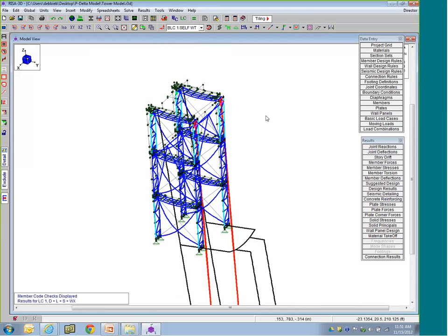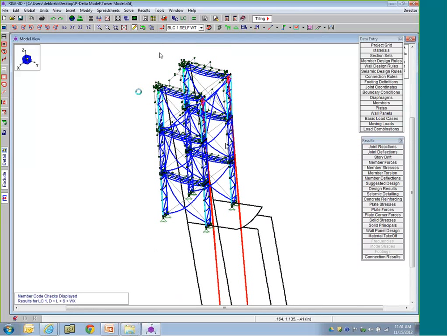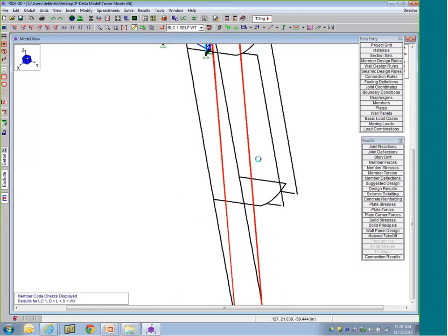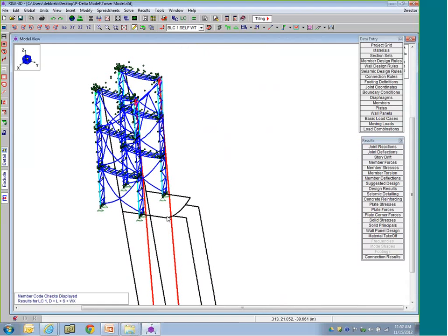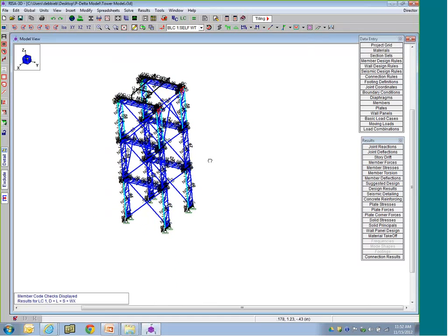So this is kind of where we start to look at what's happening, but it's hard to tell because it looks like the entire frame there is falling as it goes. So what we can do is start to see what might be the whole mechanism, where is the part that we have some failures at. So instead of looking at each single one of those members, because there's a lot of members and they're all deflecting together, which is a clue that these are all actually okay, it's just something that is failing as it goes. So let's go back to this a little bit.